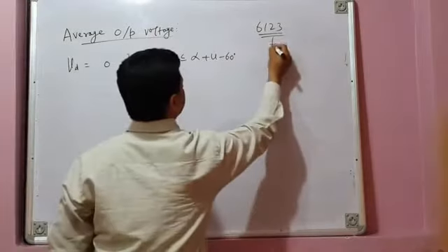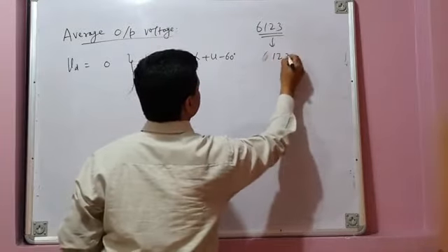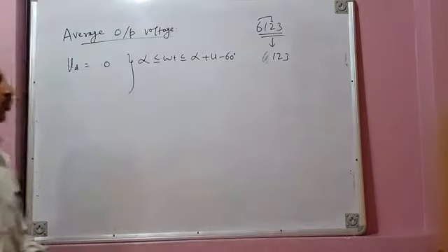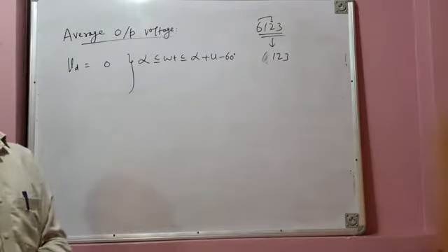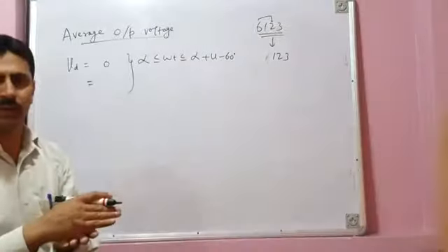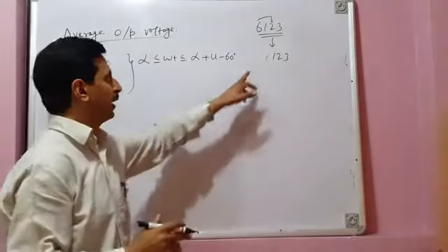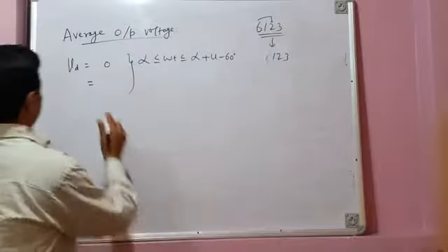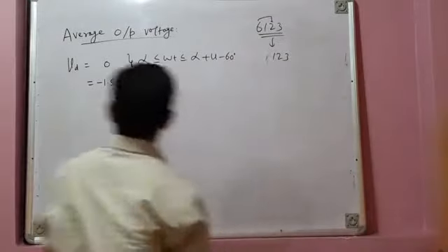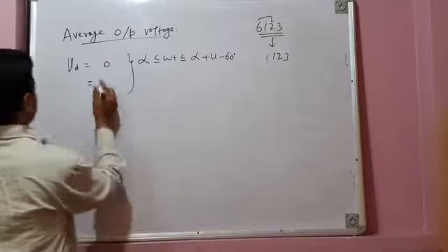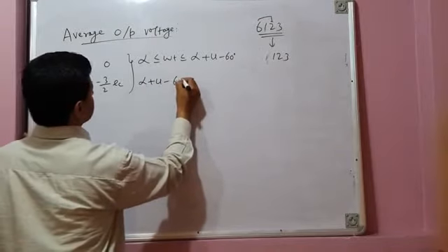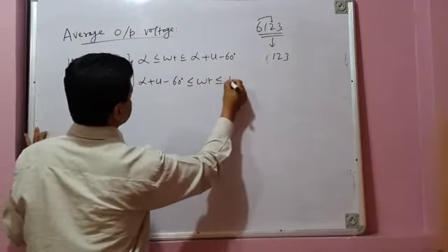And then this 4 valve conduction will be followed by 3 valve conduction, that is 1, 2, 3. When commutation between 6 and 2 is over, 6 is out, 2 is in, so it gives 3 valve conduction 1, 2, 3. And 3 valve conduction is there for 120 minus mu degrees. And what is the load voltage when 1, 2, 3 valves are conducting? Few moments back we have drawn the equivalent circuit, and we have found that when 1, 2, 3 valves are conducting, our load voltage is minus 1.5 EC, or I can say minus 3 by 2 EC. So load voltage is minus 3 by 2 EC, that is from alpha plus mu minus 60 degrees to alpha plus 60 degrees.